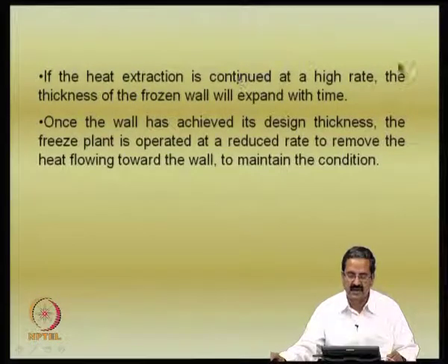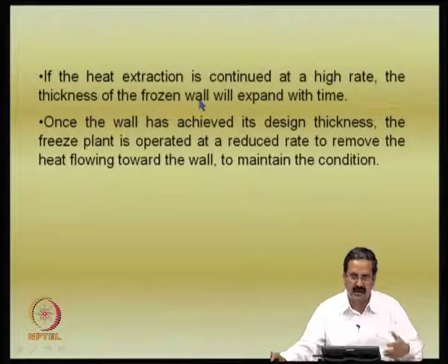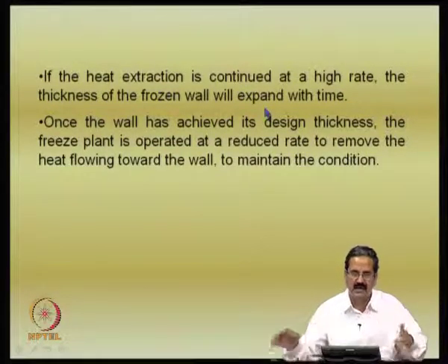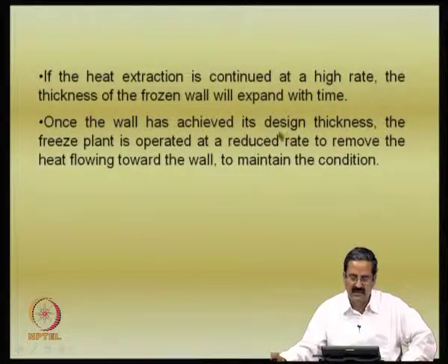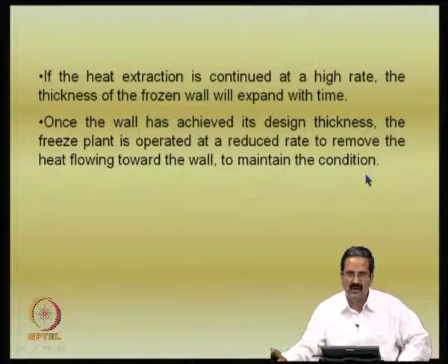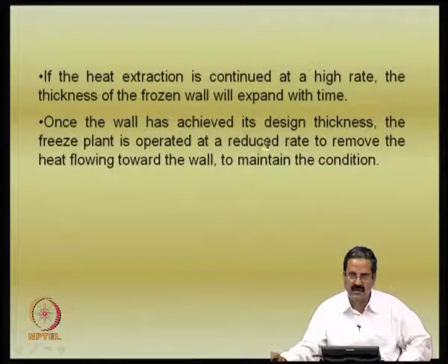If the heat extraction is continued at a high rate, the thickness of the frozen wall will expand with time. For example, you are trying to remove the heat from the system, that heat you are trying to recover actually. So, the thickness of the frozen wall will expand with time. The higher the rate, the higher the expansion of the wall. Once the wall has achieved its design thickness, the freezing plant is operated at a reduced rate to remove the heat flowing towards the wall to maintain the condition.